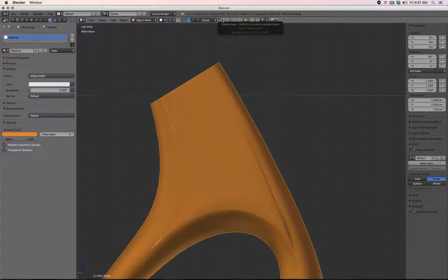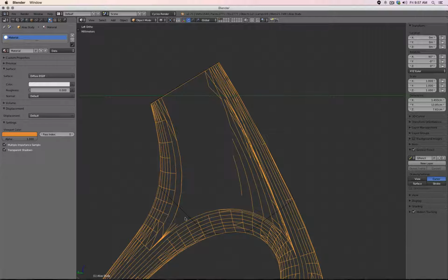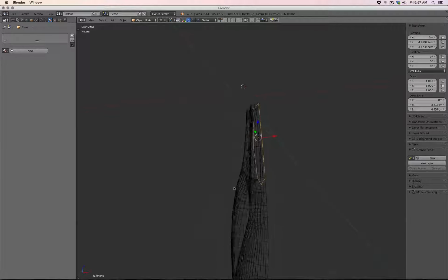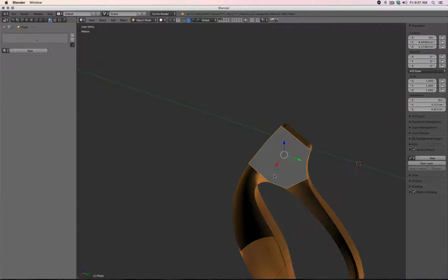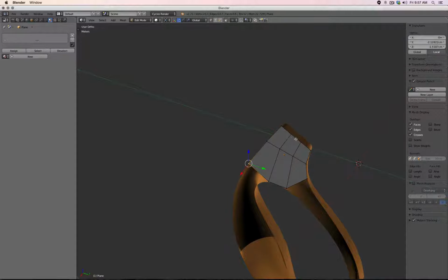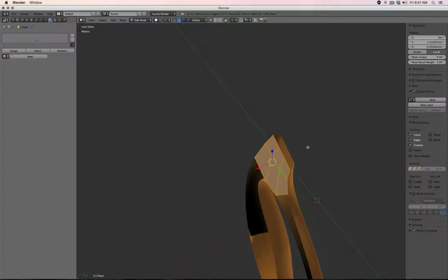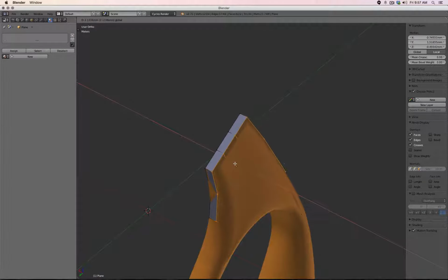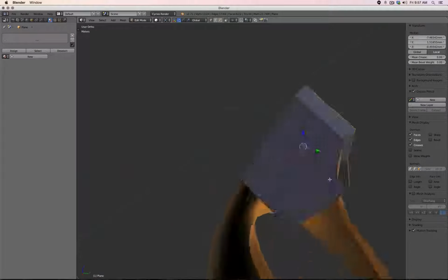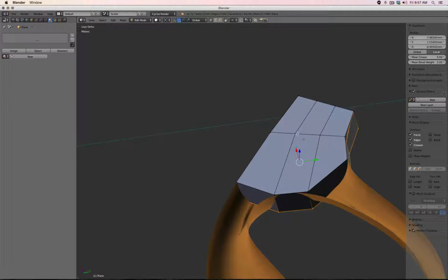So it's shift click this one, click on my object, there it is, so it's inside, and I have to extrude it. So I go into edit mode, select everything, press E, escape, and move this one out. Maybe till there for the moment. And then I go back and select actually those edges only.